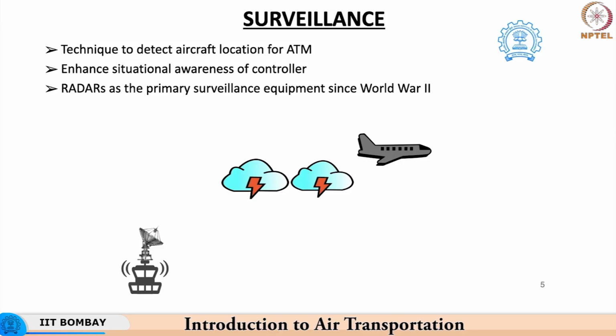So, it began by making use of the most rudimentary form of radar services, which is called the primary surveillance equipment. How does this radar technique work? Firstly, a signal is transmitted by the radar towards the subject aircraft. This is called the transmitted pulse.